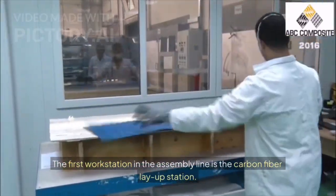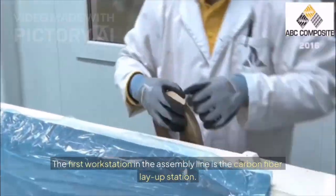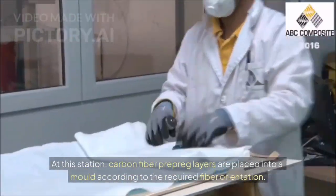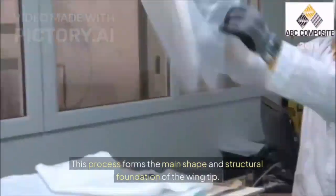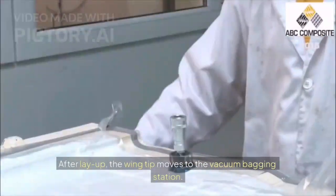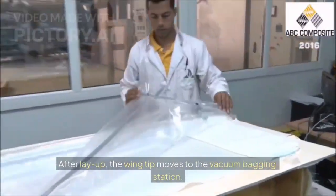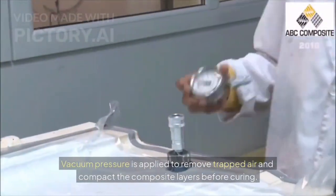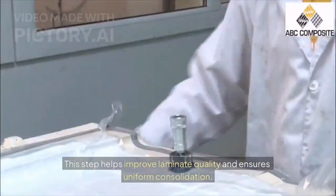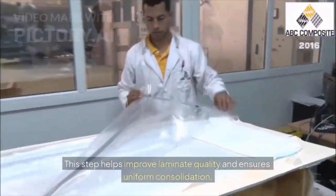The first workstation in the assembly line is the carbon fiber layup station. At this station, carbon fiber prepreg layers are placed into a mold according to the required fiber orientation. This process forms the main shape and structural foundation of the wingtip. After layup, the wingtip moves to the vacuum bagging station. Vacuum pressure is applied to remove trapped air and compact the composite layers before curing. This step helps improve laminate quality and ensures uniform consolidation.